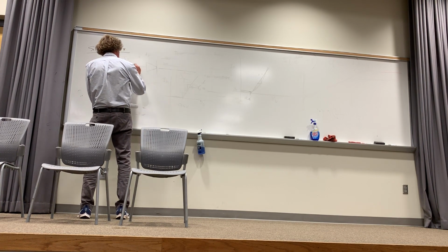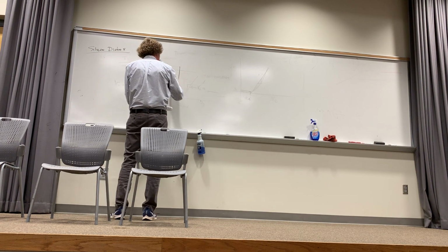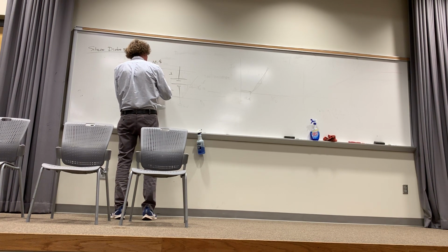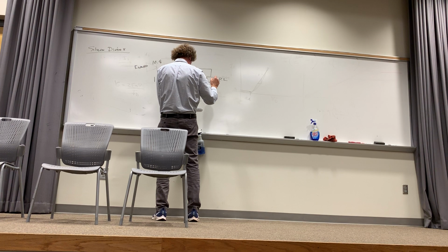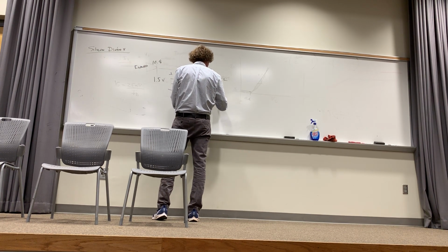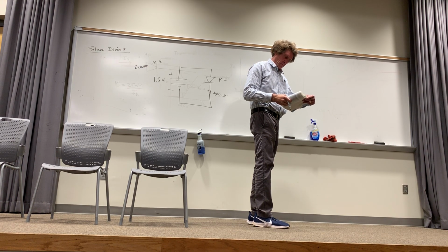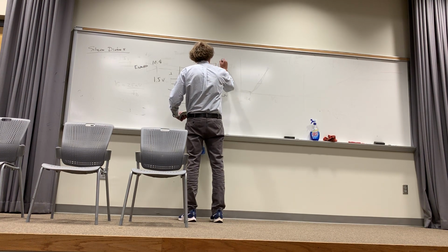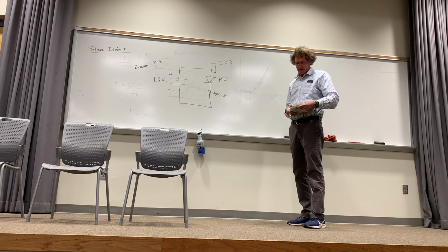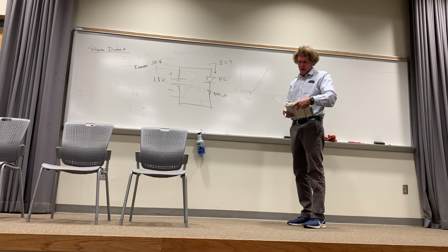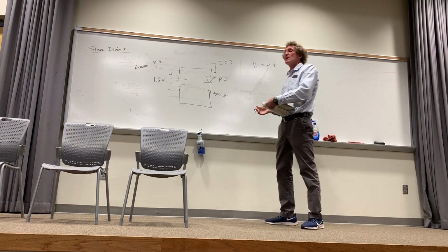We're going to do this example. This is in the book, if you're wondering. 10.8. Our goal is to find the current I. Now here are the conditions that he gives. Because that 0.6 of a volt is something that is adjustable, it says that it has a forward break voltage or threshold voltage of 0.7 volts. So it's going to say until we get a forward voltage of 0.7 volts, no current flows. Do you follow me on this?